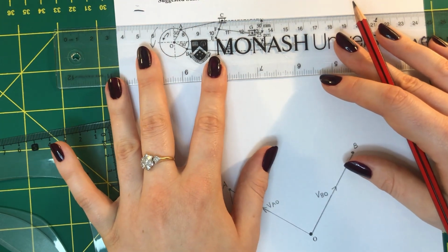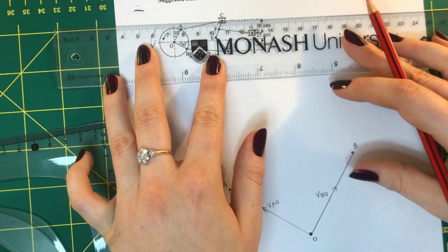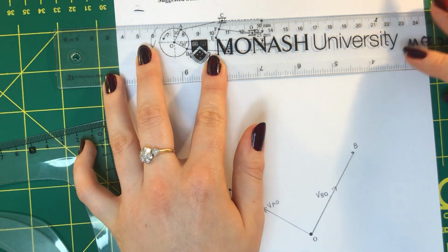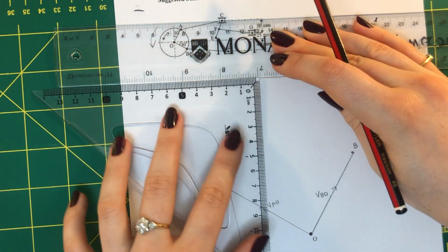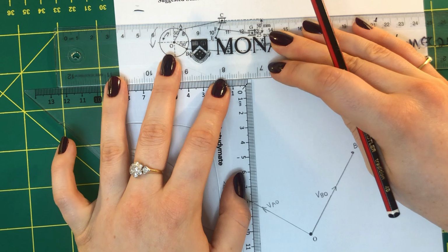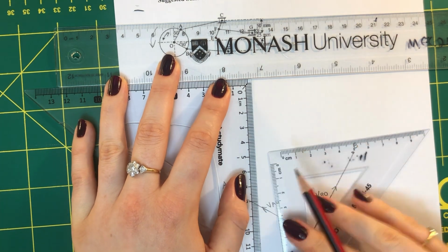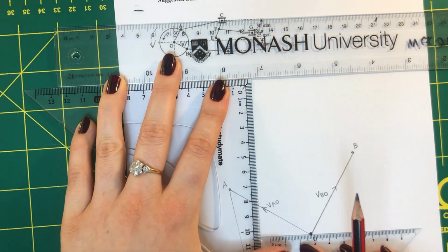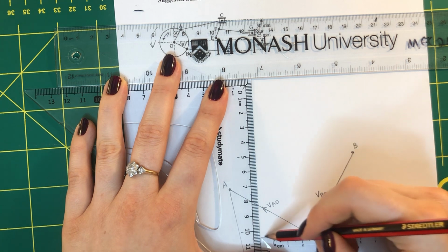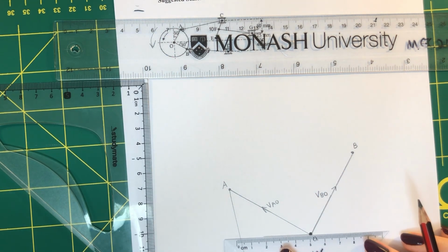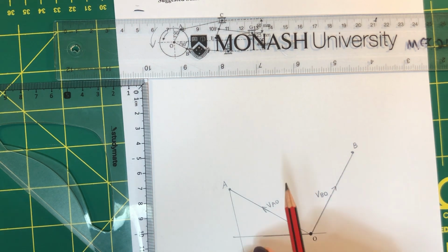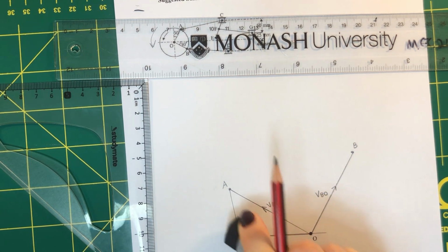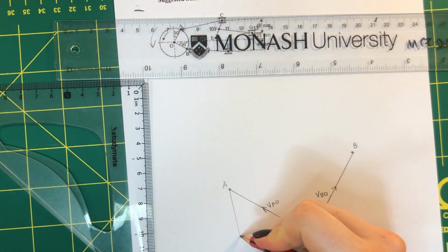So this slider has linear velocity. I'm putting my ruler against the direction of motion, and I draw a line that's parallel to that direction of motion. So I can use 2 set squares for this. So I'm extending this line across, and where these points cross, that is my point C.